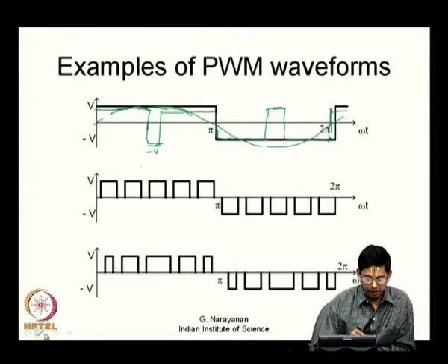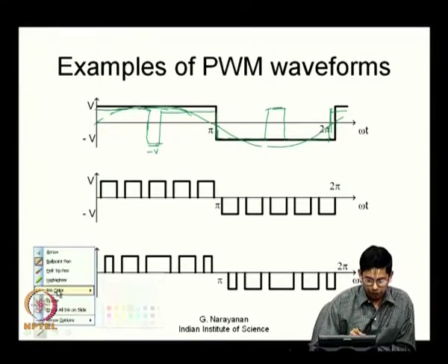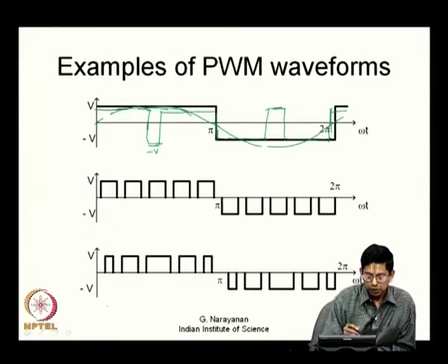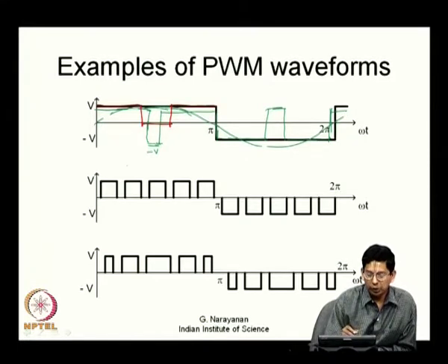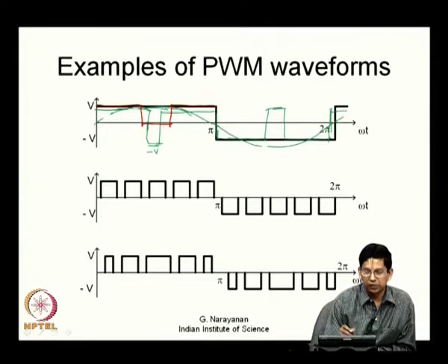So, it is better to apply a slightly different kind of a waveform. So, let us say you apply the same plus V here, there is a notch as shown by the red colored waveform, but during this notch the voltage applied is only 0, it is not equal to minus V. The same way you go around, you apply a notch.